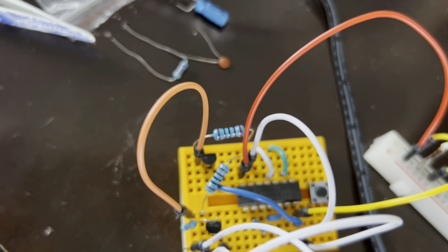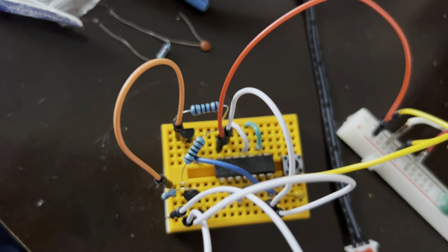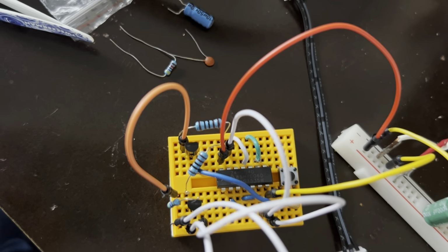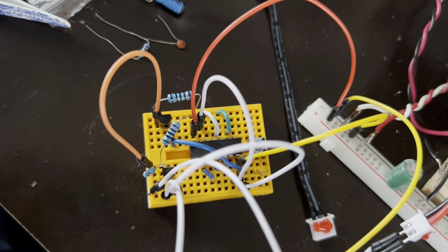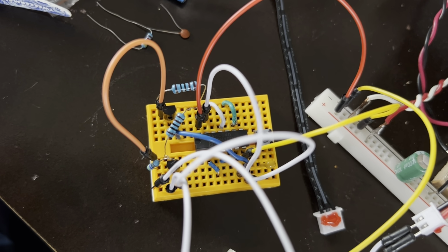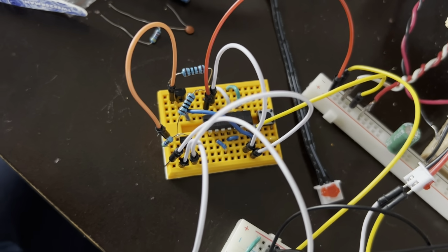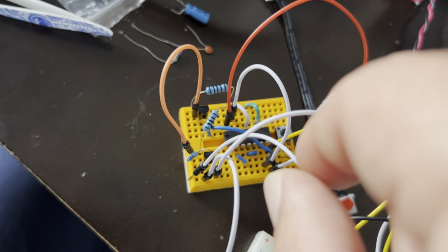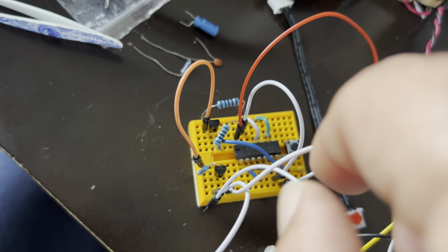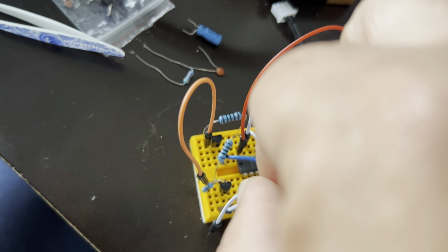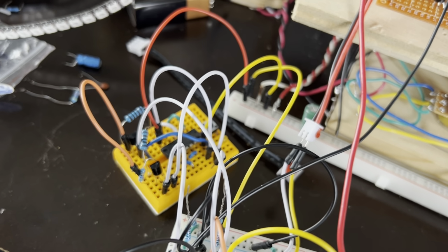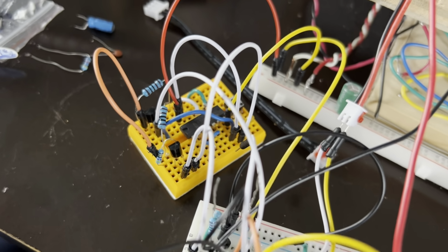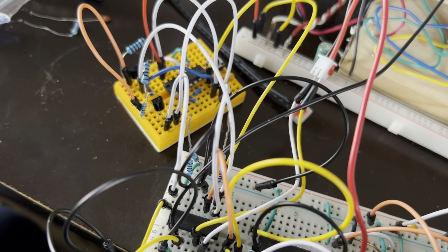So instead, I used 2 transistor-based inverters, and you can see them right there. One transistor there, one transistor there, and it's a 2N2222 NPN transistor. And when I use the transistors to delay the circuits, let's connect this up and see what we can do here. Now I have it connected properly, finally. Sorry it took so long. Now I have it going through those 2 transistor-based inverters.